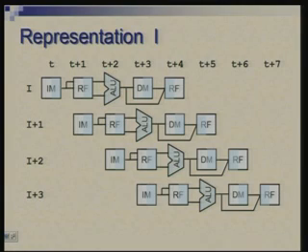Let us go back and see it here. For example, instruction I is writing into the register file in cycle t plus 4, whereas instruction I plus 3 is reading from the register file in the same cycle. But the kind of design we have assumed for the register file, we have said that it can do reading and writing simultaneously.